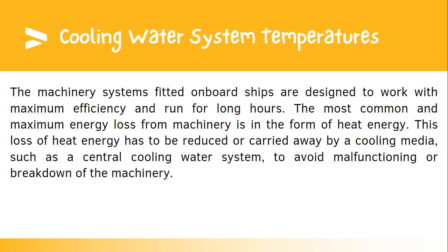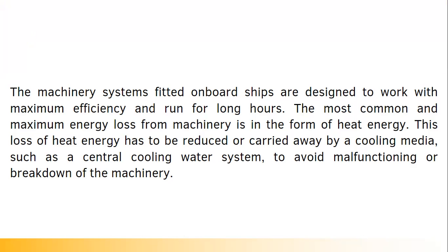The machinery systems fitted on board ships are designed to work with maximum efficiency and run for long hours. The most common and maximum energy loss from machinery is in the form of heat energy. This loss of heat energy has to be reduced or carried away by a cooling medium, such as a central cooling water system, to avoid malfunctioning or breakdown of the machinery.